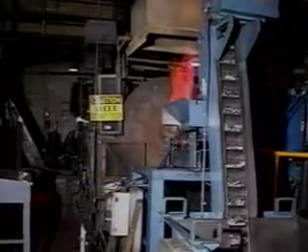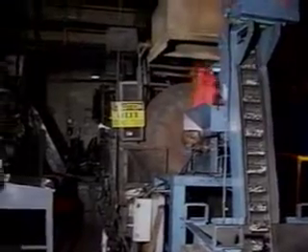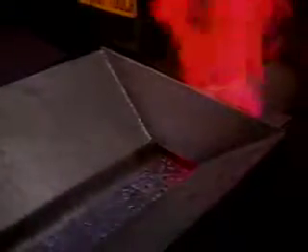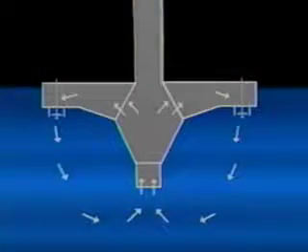Many heat treat processes employ continuous furnace designs where the parts to be heat treated are loaded on a belt, which then pass through the furnace and then drop from the belt through a chute zone into the quenchant. The parts are then removed from the quench tank using another belt and run onto the receiving line or basket. Numerous chute quench systems have been designed. Some of those are illustrated here.